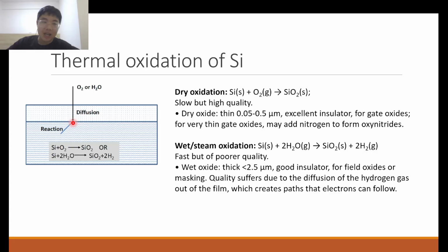Now, how do we know that? Just for your information, we can know that by growing the SiO2 layer using normal oxygen, then changing the isotope of oxygen and continuing to grow the silicon dioxide layer. Then I can observe, using techniques like maybe NMR related techniques, where the layer of SiO2 that's formed from the different isotope is formed.